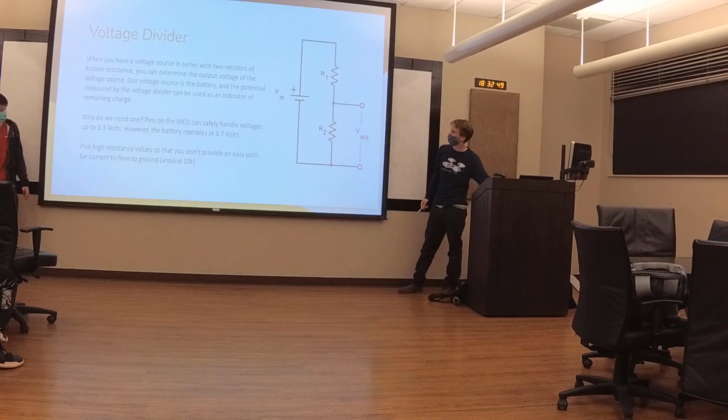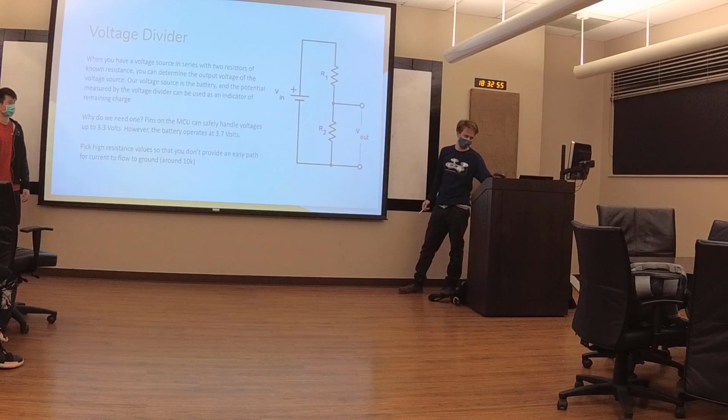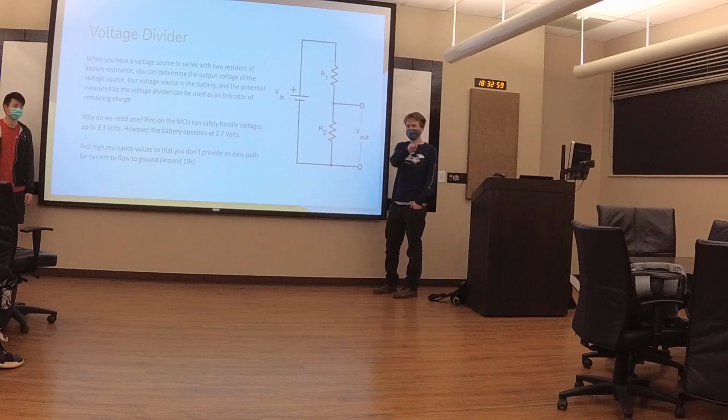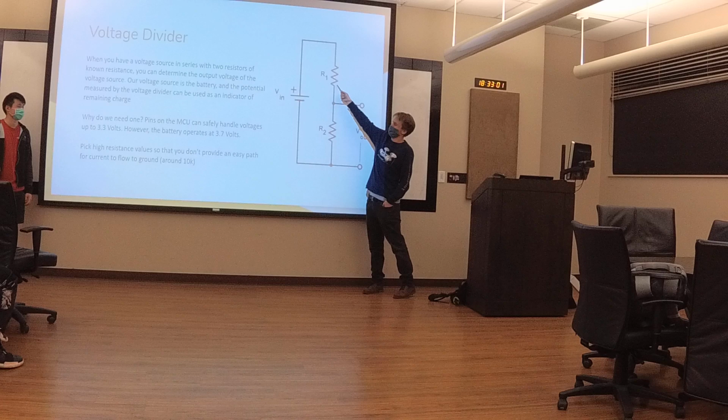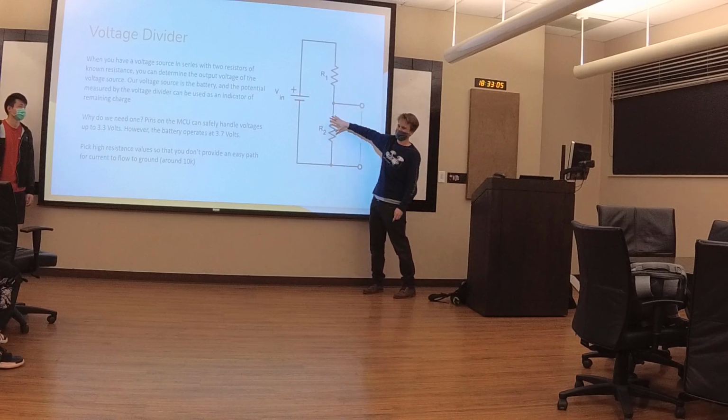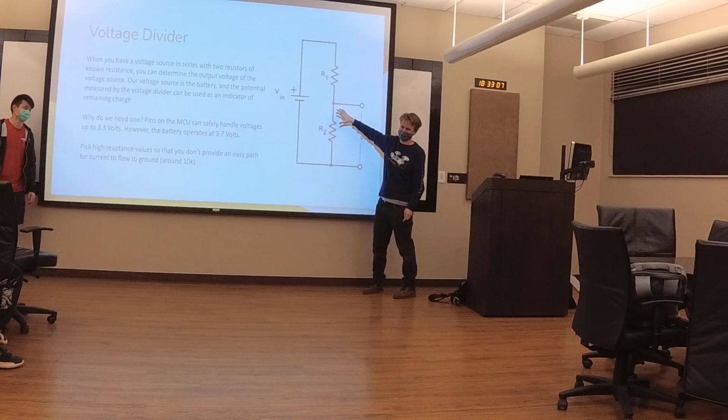And FYI, I think for our values, we're just looking for R1 and R2 to both be 10K. 10K, okay, 10K is reasonable. Here's the other thing. You asked about noise, right? You might think, I'm going to make this 1,000,000 ohms, and I'm going to make this 1,000,000 ohms, because that way no current's going to flow through here, I'm not going to waste any energy, right?